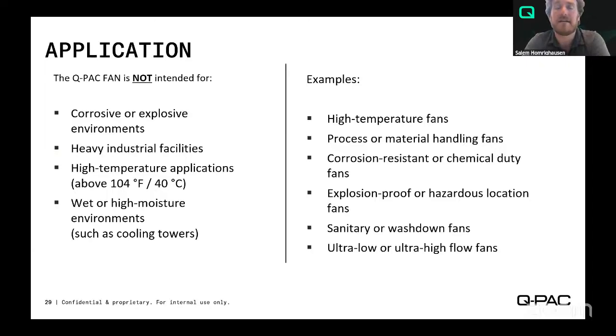So the Q-PAC fan is not intended for corrosive environments. So think natatoriums or pool houses. Typically, there's enough corrosive material in the air that would prevent you from wanting to use the product. That being said, it's all about what the end user needs, especially in a retrofit situation. If someone loses a fan and they need to move air for that space immediately, Q-PAC does have quick build options. We have a standard 3 to 4 week lead time, but there's a 2 week, 1 week, and 48-hour quick build option pending production approval. So if you have more questions about ordering one or an application you need help with, you can reach out after the presentation.